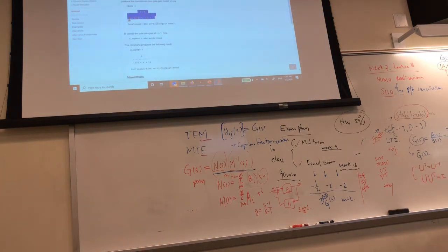You can see there's a cancellation. I really want to remove this s minus 1. So what do you do? You just say minreal of Cloop. Cloop is an LTI object. So then you get Cloop minimum, and after you've done that, you cancel out that term.